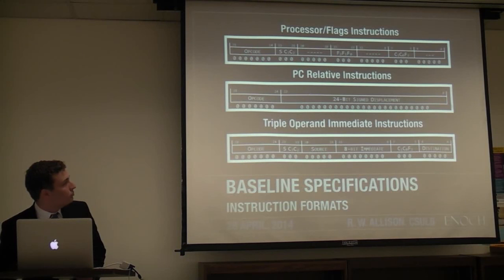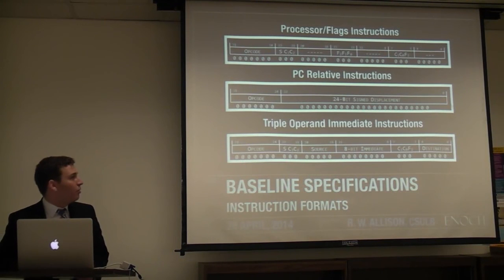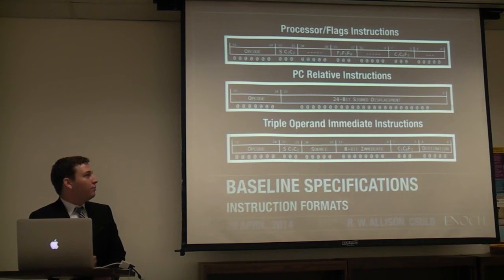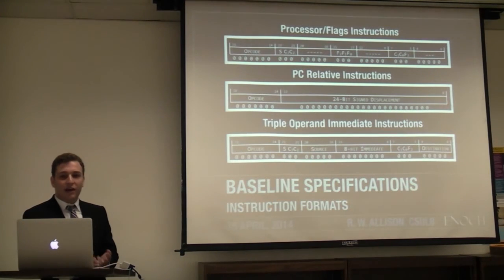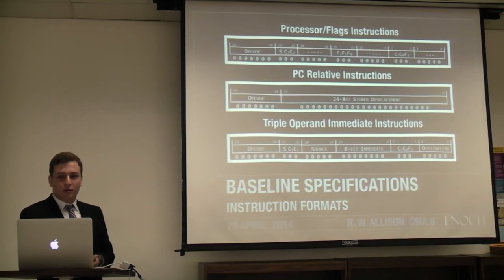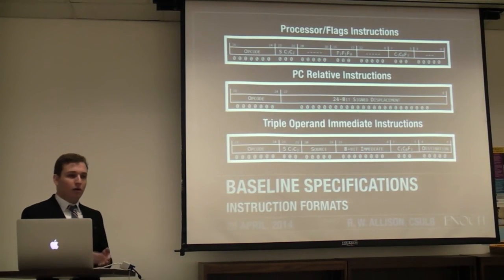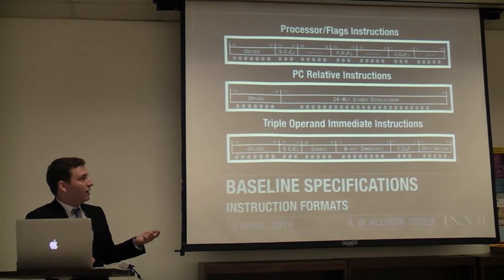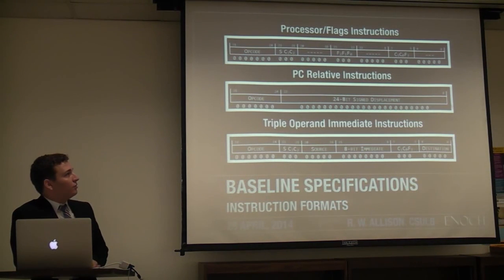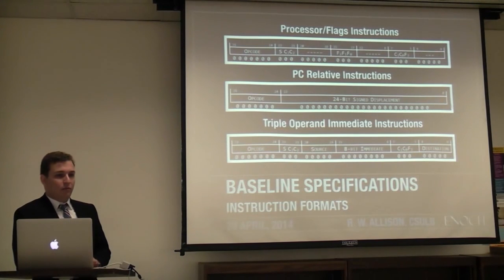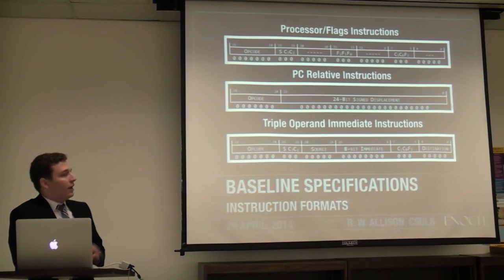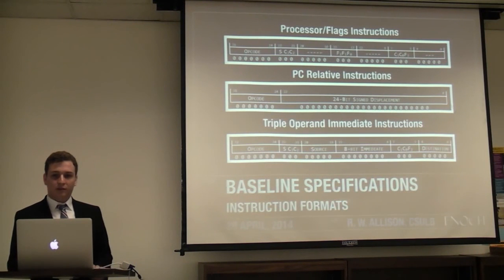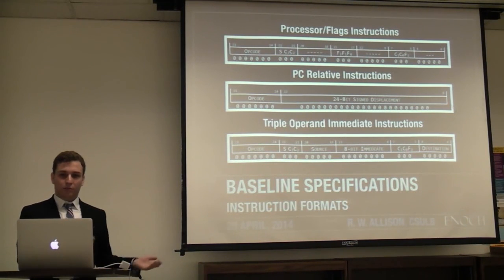Can you talk about why the PC rel does not have a suppression, the S bit? Okay, yeah. So one thing about the PC relative, neither sets the flags, and it's almost always conditional anyways, or there are PC relative that are conditional, so it's unnecessary and impossible to use the conditional execution of instruction or conditional setting of flag. So when there is a PC relative instruction, the hardware that handles that ignores it because it's impossible to use our enhancements on a PC relative instruction.